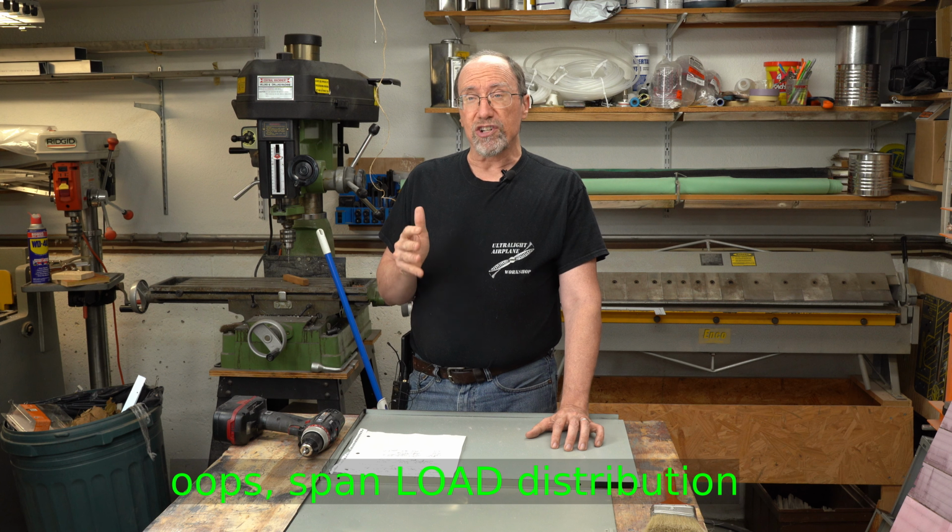So we're getting much closer to being able to work on the structural design of the rudder and the vertical stabilizer on the UWS-1 Ultralight Airplane. But we have a little more to do. We've done the span-wise chord distribution. The next thing to work on is going to be the chord-wise load distribution. Once we get that done, then we can separate the load between the rudder and the vertical stabilizer.